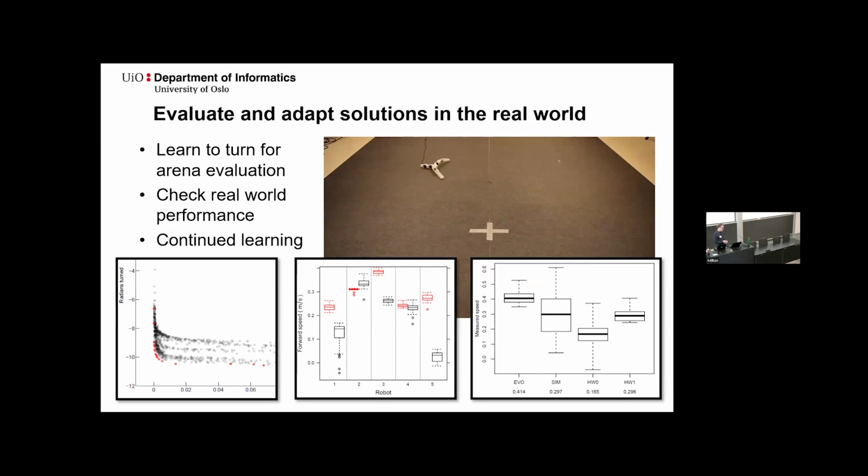So in this evolutionary work, we didn't do any learning in the evolutionary process in the simulator, but we did a little bit of learning in the end. I think if we had more computational power, we could potentially also have done learning in the simulated stage. The controller for this type of robot is a central pattern generator based approach with some joint inputs from the joint position to the controller. So it's a kind of robust control system that can easily be tuned to new morphologies.